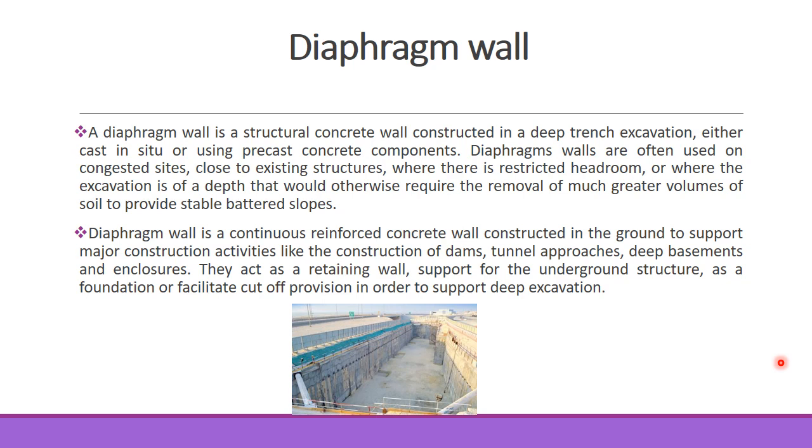A diaphragm wall is a continuous reinforced concrete wall constructed in the ground to support major construction activities like construction of dams, tunnels, and deep basements. These act as a retaining wall, a support for the underground structure as a foundation, or a cut-off facility, in order to support the deep excavation. In the picture, you can see this wall is called the diaphragm wall.